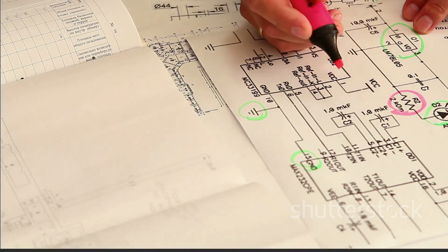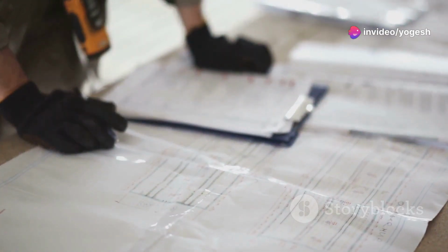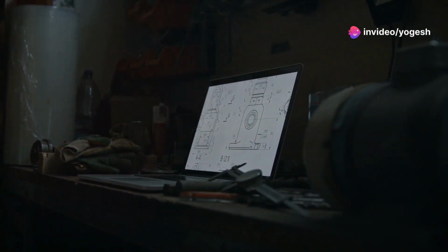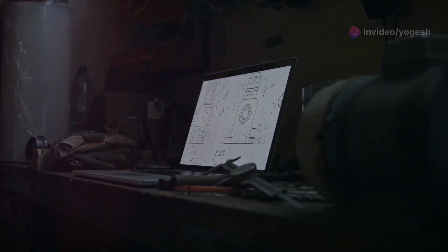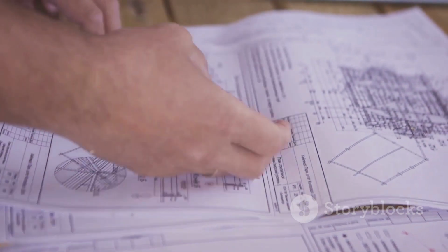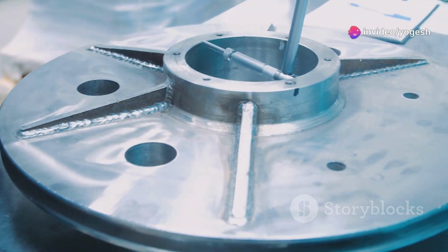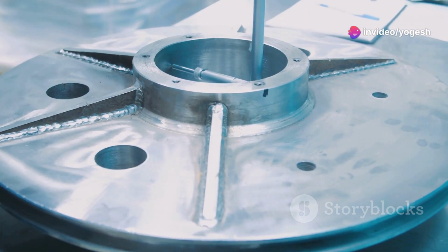Don't forget notes and specifications. They're critical. Always specify material, heat treatment, and surface finish. Include a complete bill of materials for assemblies. Every part, every detail. General notes cover instructions like deburring or special inspections. Missing specs can ruin a project, even if the geometry is perfect.